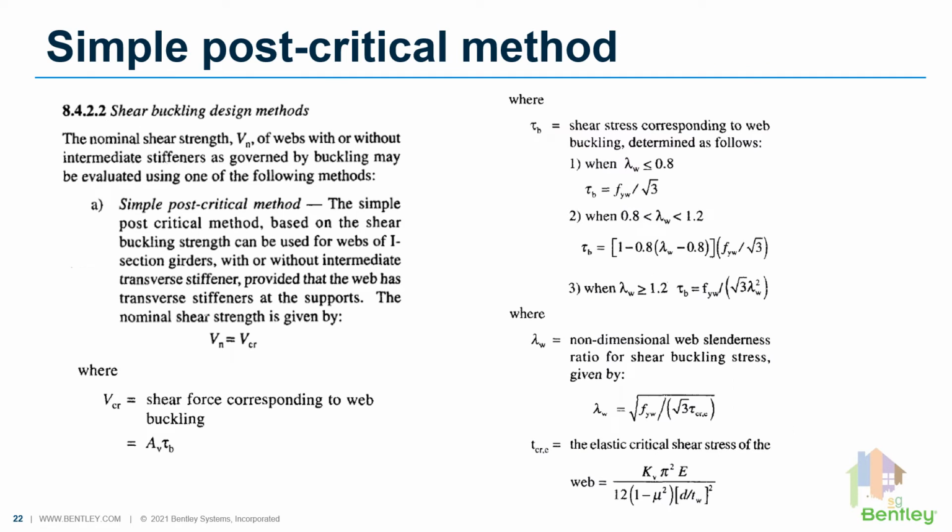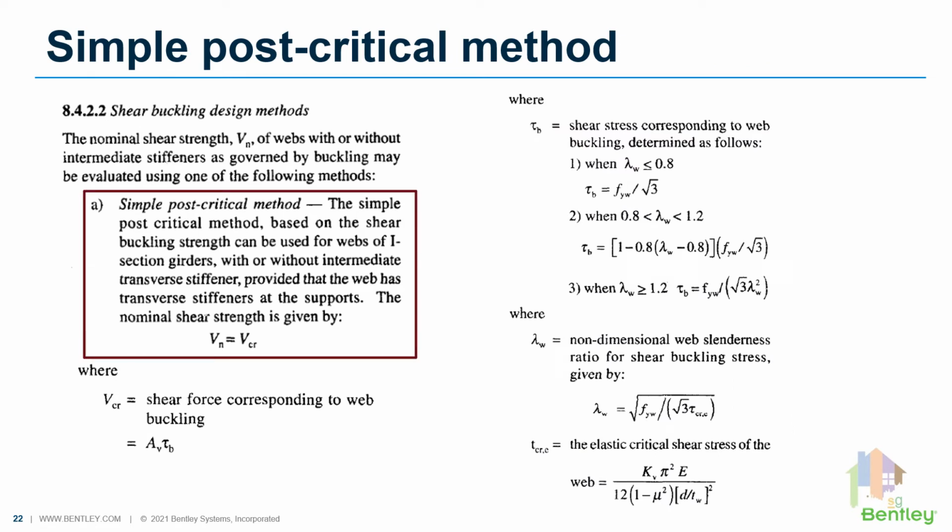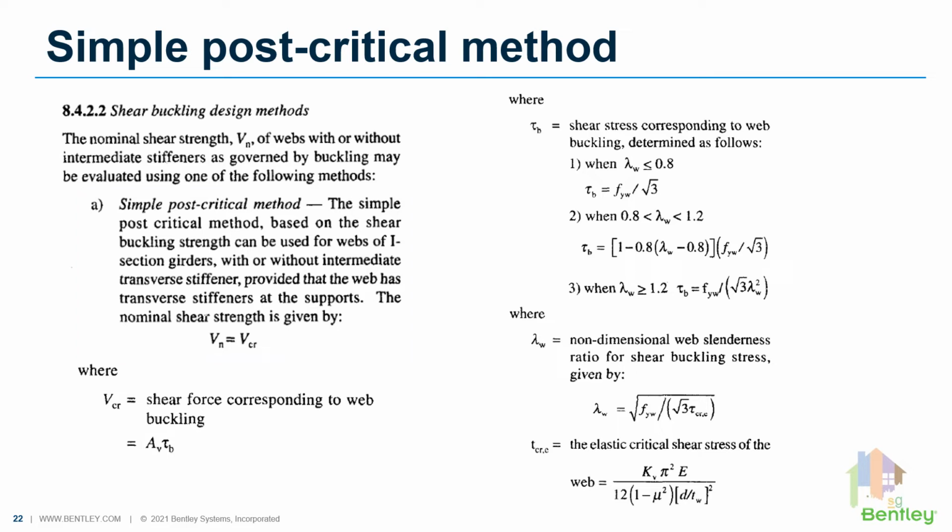Instead, the simple post-critical method as per clause 8.4.2.2a is implemented to calculate the nominal shear strength for shear buckling. The tension field method is not implemented yet. Also, stiffeners cannot be modeled or designed in STAAD. You can provide stiffener information, and on the basis of that, shear capacity is determined.